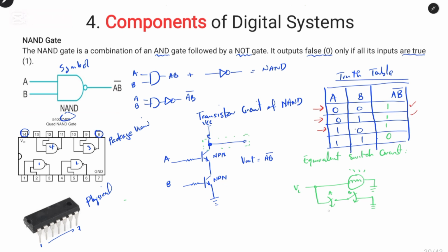Combination 3, we have switch A closed and switch B open. Even though switch A is closed and switch B is open, there won't be a complete circuit in this region because switch B is in the open position. Therefore, current will flow towards the lamp and towards the ground, which causes a closed circuit, which allows the lamp to switch on. And we have 5 volts at input A and 0 volts at input B.